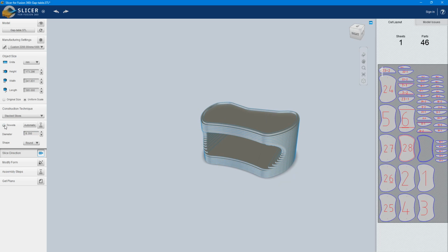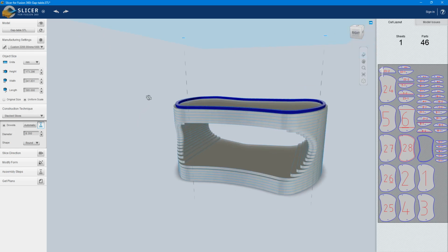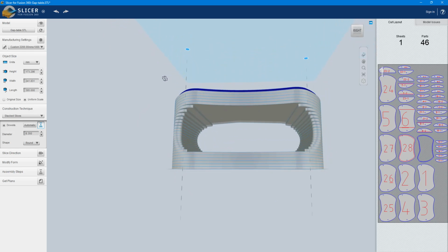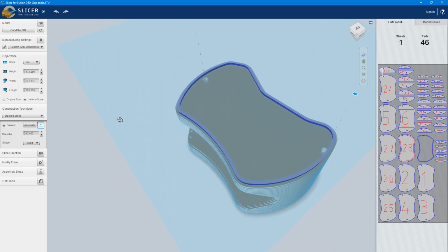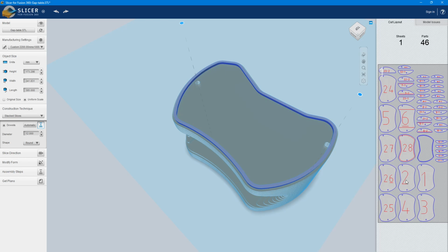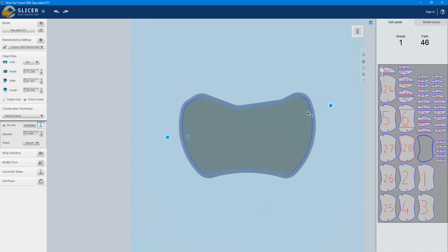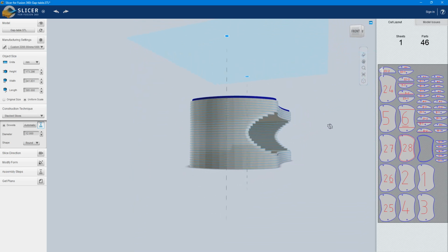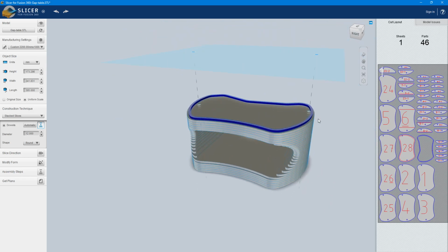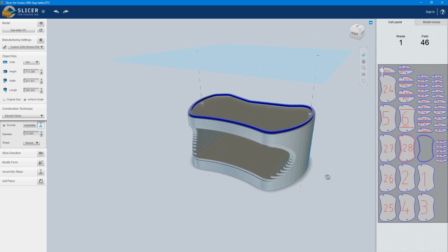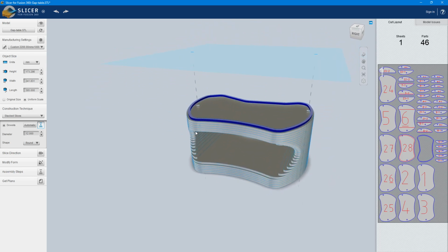One important thing is we want to put the dowel pin, and the dowel pin is there to get the alignment and consistency. My tool diameter is 12 millimeters, so I will simply put 12, so that we can drill the 12 mm size of the hole. We can look at the top how it is, and we can see it is going through all of them. The blue color is representing that this is not having the dowel pin alignment, so you will be responsible for the alignment of the spacing.